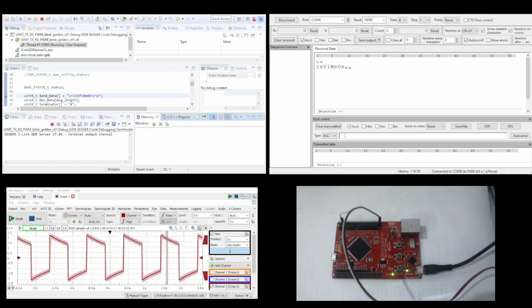Pulse width modulation (PWM) or pulse duration modulation (PDM) is a method of controlling the average power delivered by an electrical signal. The average value of the voltage and current fed to the load is controlled by switching the supply between 0 and 100% at a rate faster than it can take the load to change significantly. The longer the switch is on, the higher the total power supplied to the load.